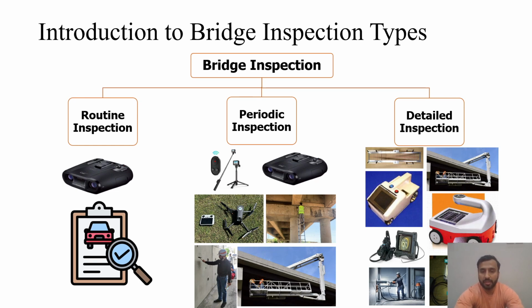of the bridges, especially underneath the bridges. So you may need to use pole cameras in case you cannot go physically close to different components. The pole camera can help you send your camera close to the components where you cannot be by yourself. Binoculars, of course, and drone cameras can also take a more overview photo from height so that the whole bridge can be captured in a single frame.